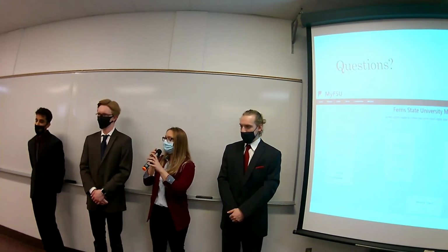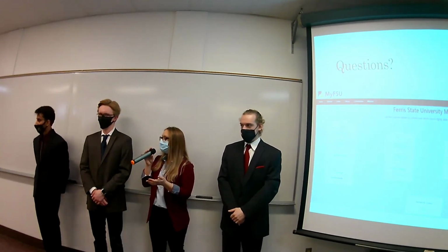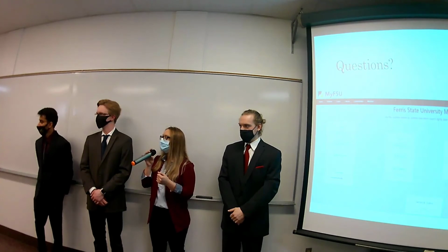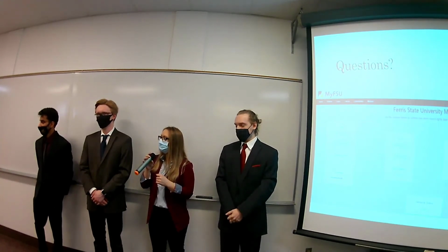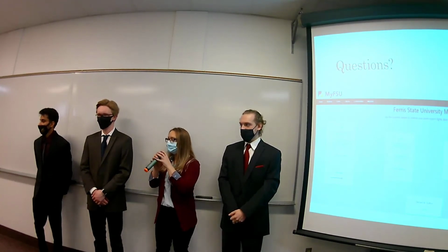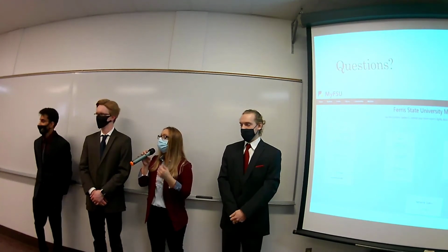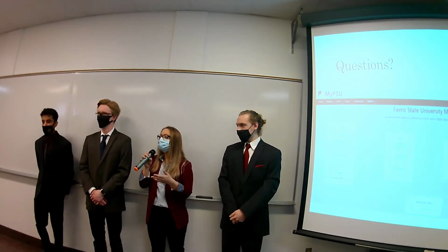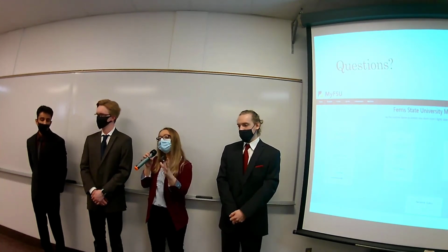So the question was, did we consider using anything other than the relay? Is that correct? Am I understanding correctly? Yes, what I meant was, right now you have either the heat fully on or fully off. I'm wondering if there's a way to modulate that so it can go 0 to 100%. So there are abilities and ways to operate your temperature and have it controlled, as opposed to having it just on and off, having it be gradual.